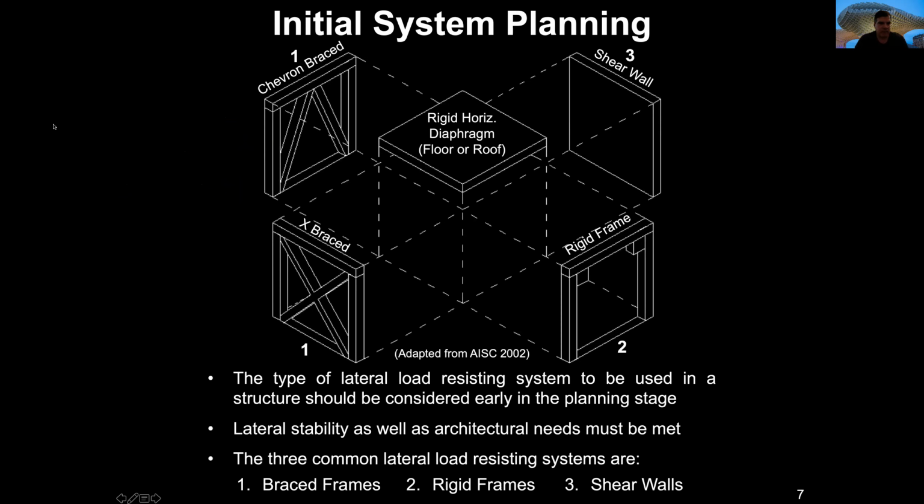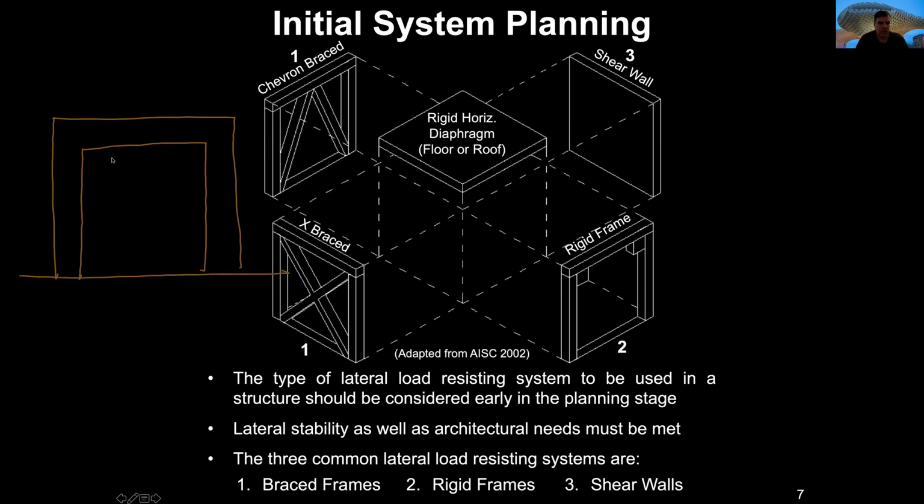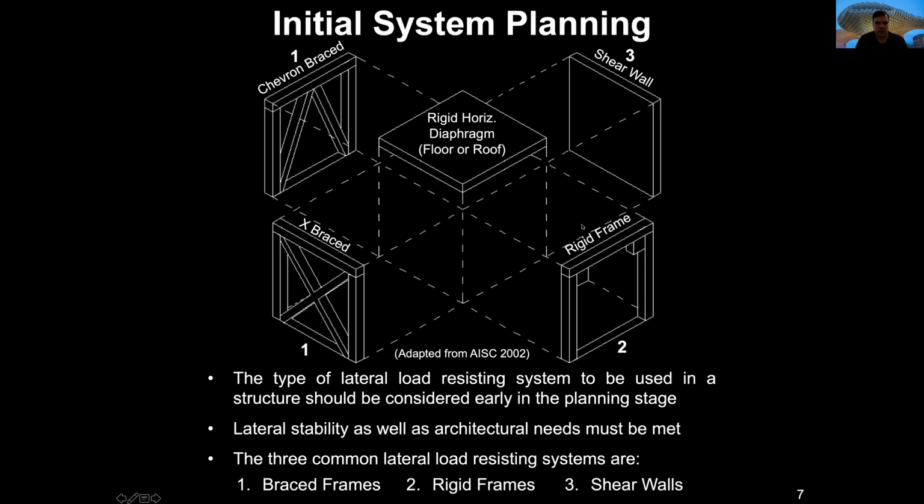When we have a building made out of concrete, we don't have that problem because usually concrete is much thicker. The material that is used is very thick, and there is a strong joint at this point. Well, there is an intrinsic rigidity. But in the case of steel, that doesn't happen. The frame is rigid only if we have something that makes it rigid, like for example, a specific connection.